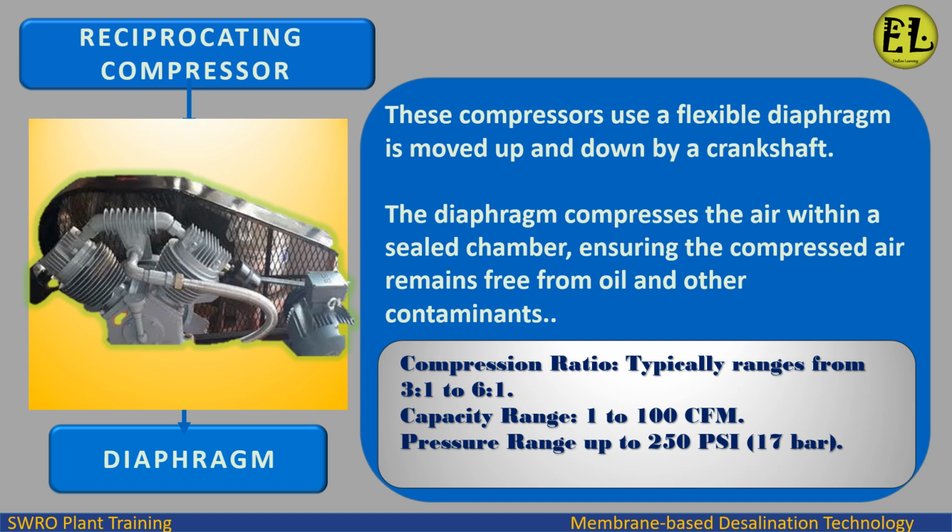Compression ratio typically ranges from 3:1 to 6:1. Capacity range, 1 to 100 CFM. Pressure range up to 250 PSI, 17 bar.